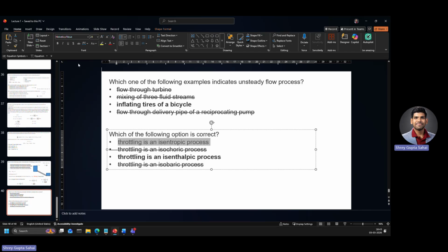Throttling process is known to be an irreversible process. Okay, this is the first process that you're learning of which is an irreversible process. Throttling is an irreversible process. We can actually see this. If you have the same enthalpy across a stream and your pressure is still dropping, we can actually see, for an ideal gas at least, that this has to be a non-isentropic process. And I'll tell you, entropy must actually increase. Okay, so let's look at this.